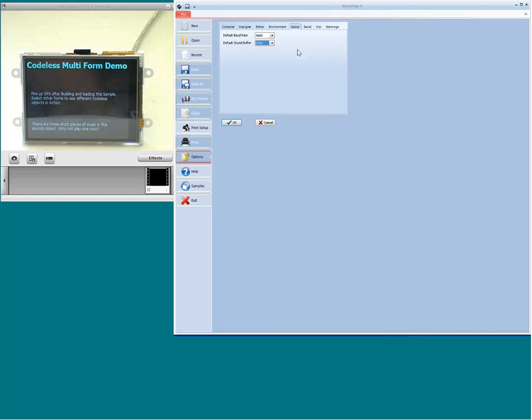It's not necessary, but I recommend it. For serial, you have the initial baud rate to the screen, and you can have a delay, and also Goldelox special features. For Visi, same message with the flash, and then you can set the default destination when you save the program. You can decide flash or RAM, it depends on you really.